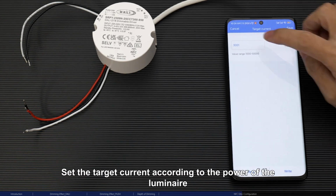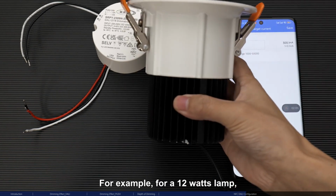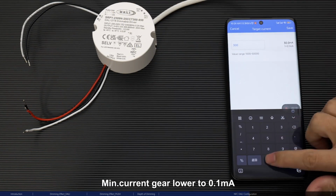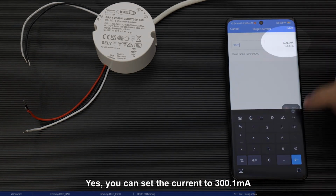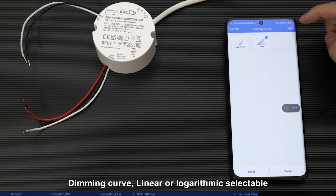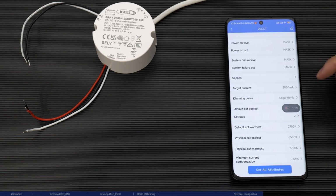Target current. Set the target current according to the power of the luminaire. For example, for a 12 watt lamp, set the target current to 300 mA. Min. current gear lower to 0.1 mA. Yes, you can set the current to 300.1 mA. Dimming curve, linear or logarithmic selectable. Logarithmic is a more comfortable dimming curve.